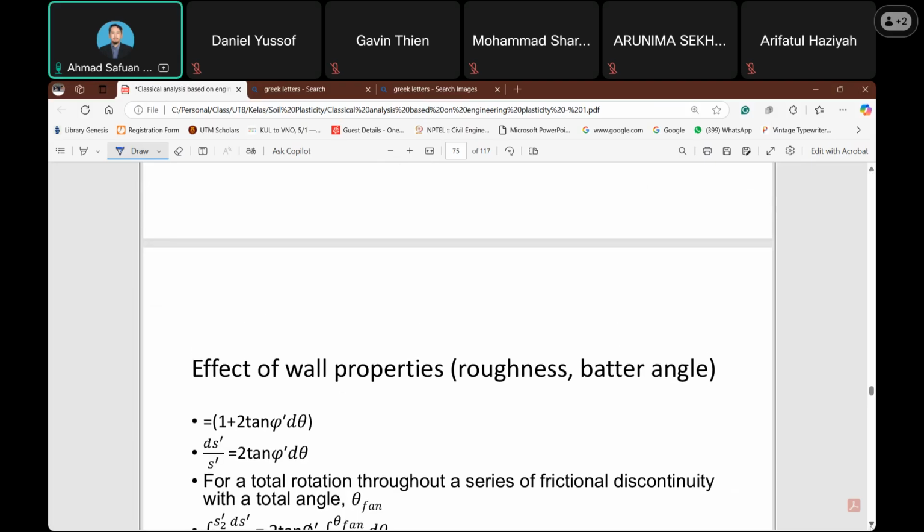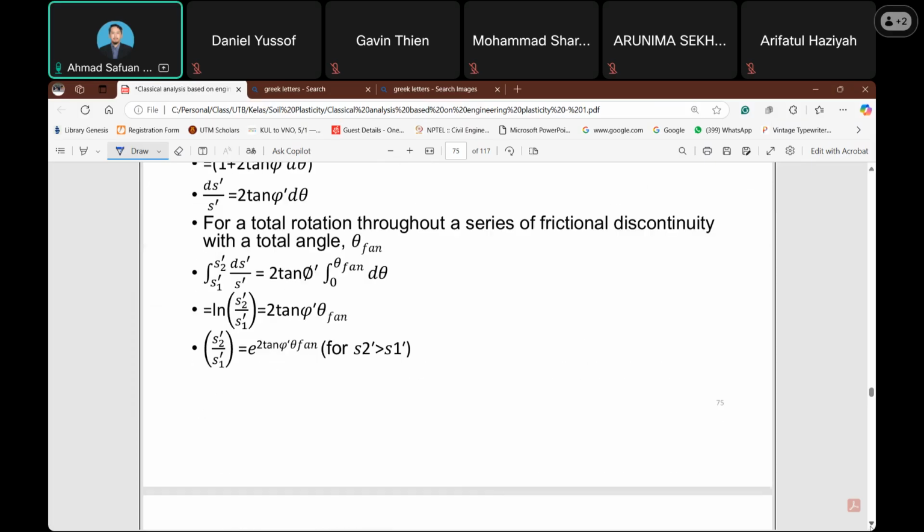Okay, then we work again. Okay, the same procedure, okay, to get the full derivations, okay, for the PA and PP. Okay, so for this, we should know that the Mohr circle for zone 1 in the active and passive side remains the same as in figure 7, the figure for the undrained case.